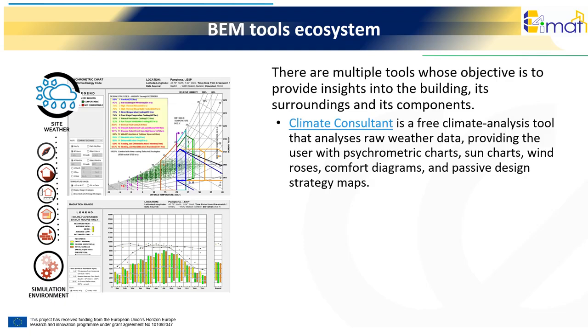In addition to the generation of the base building energy model, there are multiple tools whose objective is to provide insights into the building, its surroundings, and its components. These tools' objective is to deepen the understanding of a particular system in relation to the building model. For weather analysis and its relationship with the building's passive systems, envelope, Climate Consultant offers an understanding of local climate behavior, identifying envelope strategies and HVAC approaches before modeling.